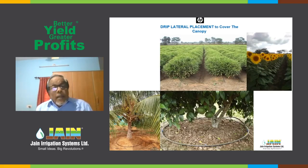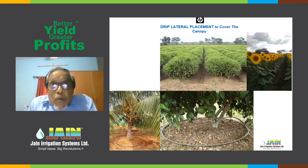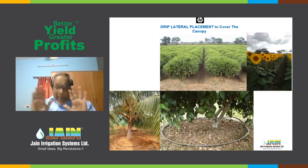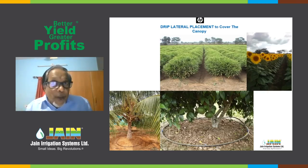There is thinking that there are 2 rows. See, the confusion comes in a reverse way. When a commercial person goes to the ground and sees there are 3 rows or 4 rows of ginger, he immediately thinks that there should be 4 rows or 3 rows of drip line. That is what I'm questioning. That is not the case. The case is, in that situation also, based on the lateral spreading distance, you can end up giving 1 drip line for 3 rows or 4 rows.